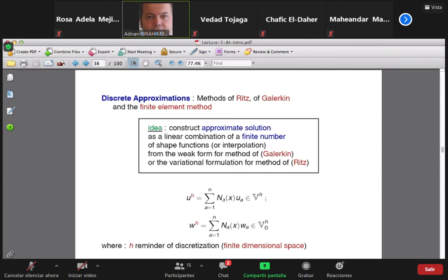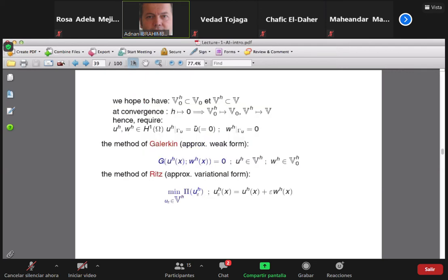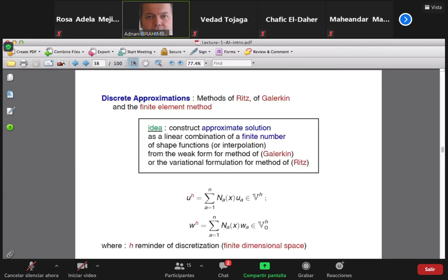Whereas if you have some other functions, you're missing so-called completeness. You're not sure that all these functions can lead coherently to representing the Taylor series. Hence, let me stick with a very simple type of illustration, where I'm going to introduce the approximation in terms of the known shape function. So you're the one who's choosing the shape function, thinking what's the best model to be used. If you take a linear shape function, that means you're taking a two-node truss bar element. If you take a quadratic, that means you're using a three-node truss bar element. We'll talk about that as we go along.